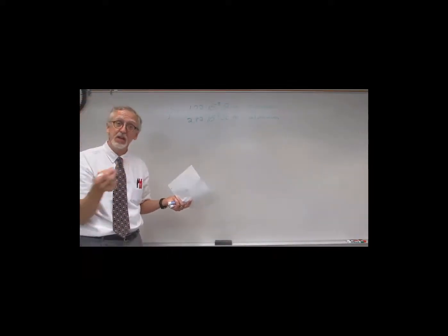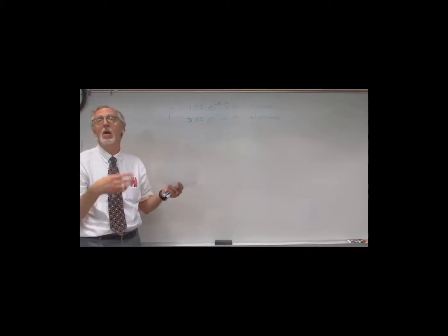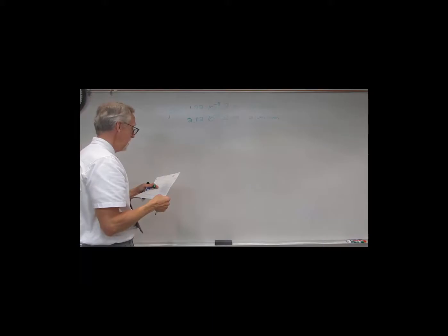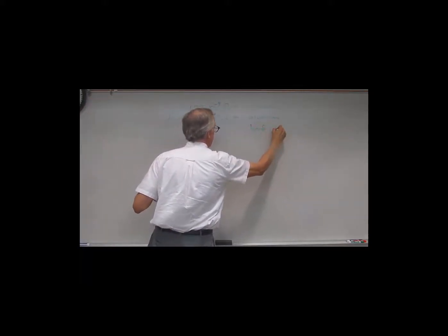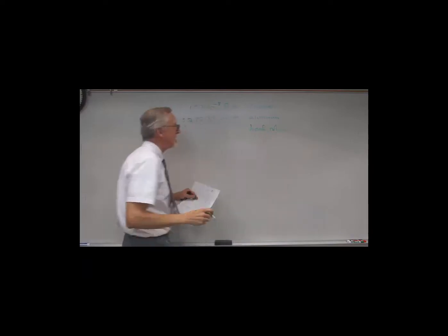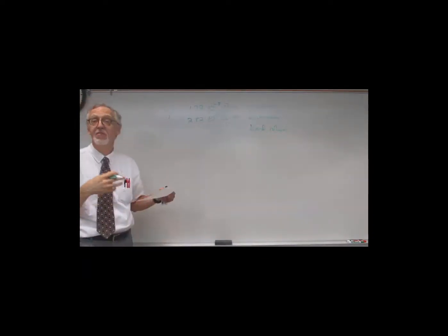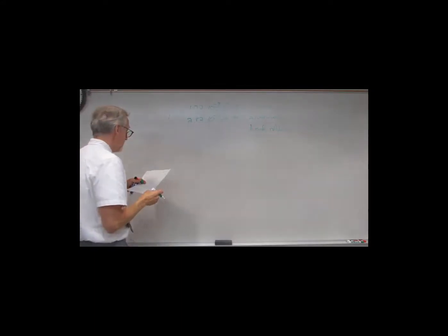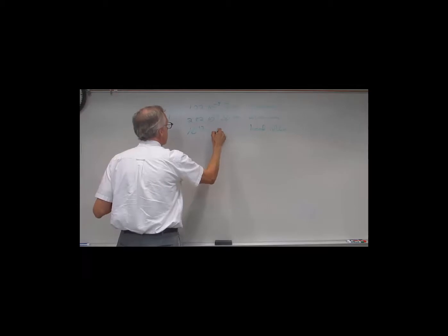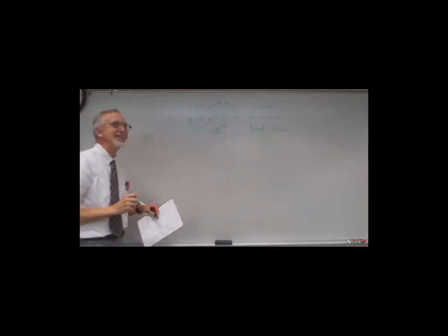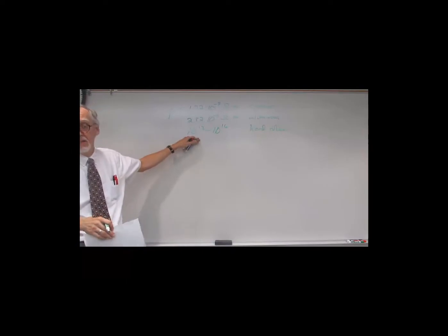Well, what's the material that goes over wires when you've got wires in the wall or something? Well, rubber or plastic, something like that. Well, rubber, hard rubber. Now, depending on how the rubber is vulcanized, depending on the different kind of rubber, it will have different values for the resistivity. But they can range from, say, 10 to the 13th to 10 to the 16th power. Extremely, extremely high values of resistivity.